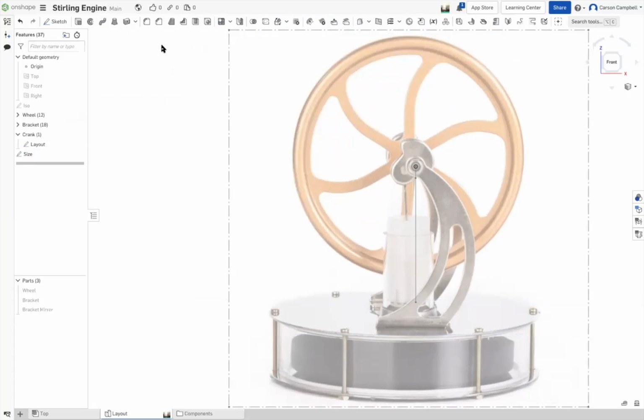Typically, when you go buy a shaft, you will say, I want my shaft to be 3mm, and you can buy shafts that are 3mm, plus nothing, minus nearly nothing. Do you want to press that wheel onto the shaft? That'd be nice. So we'll have a press fit.